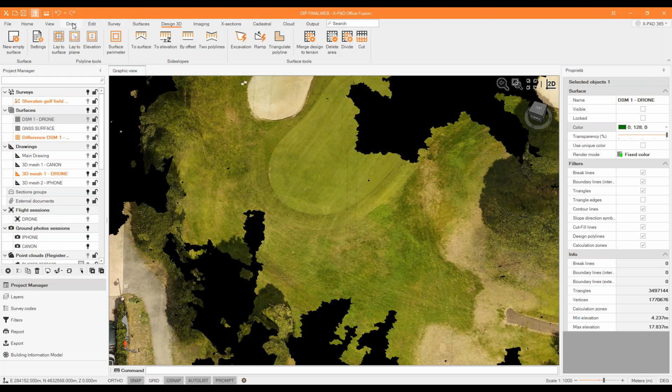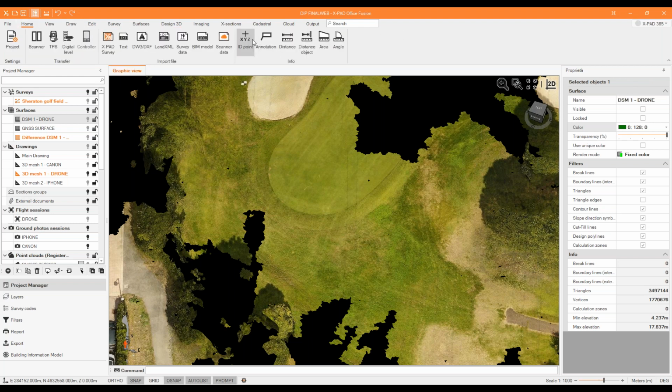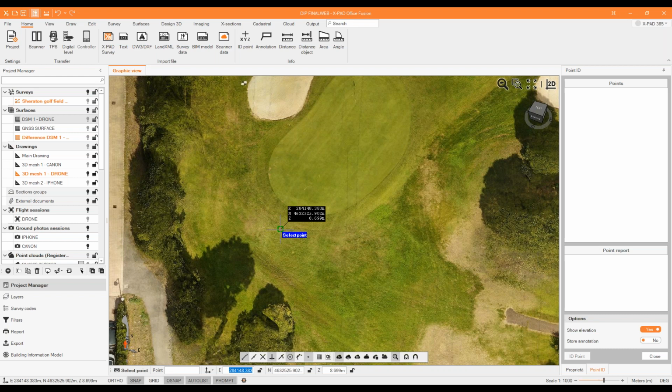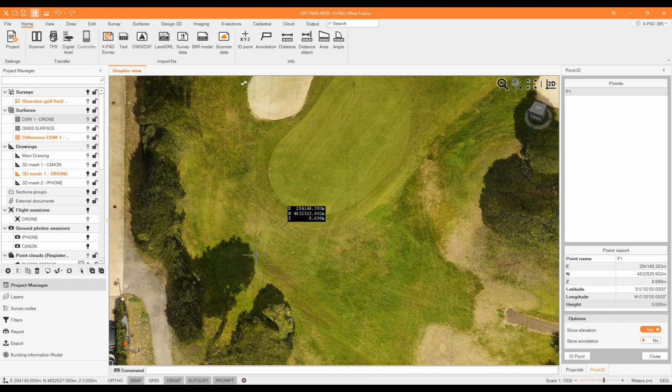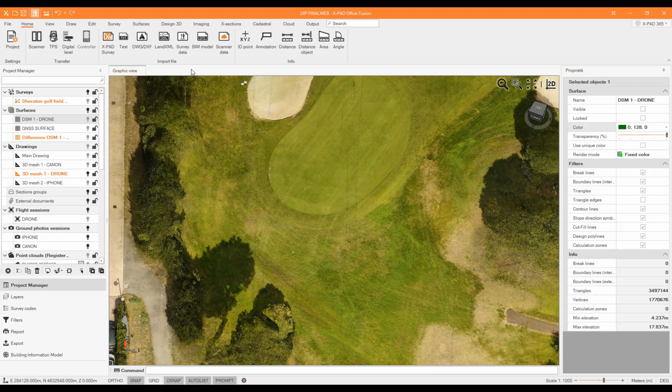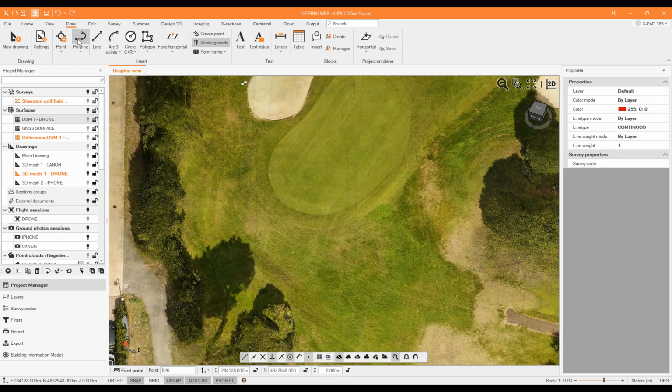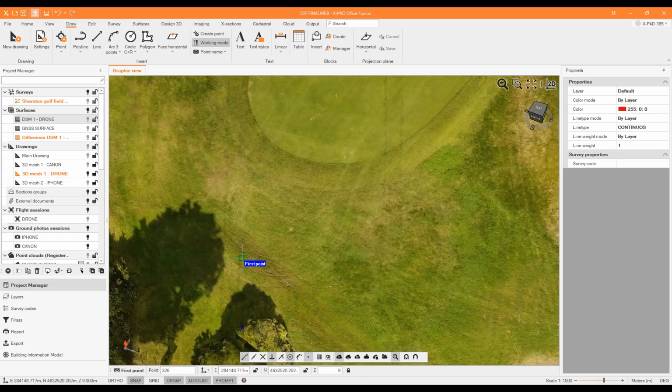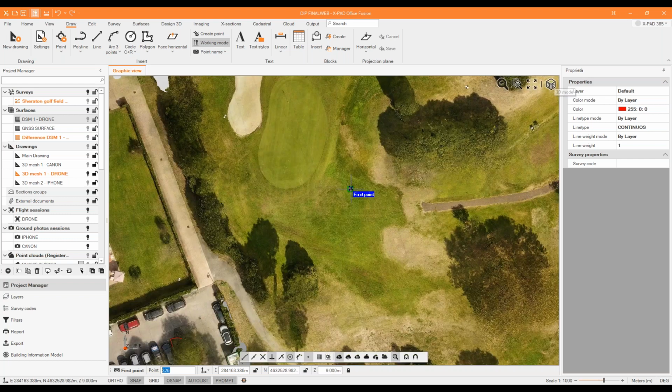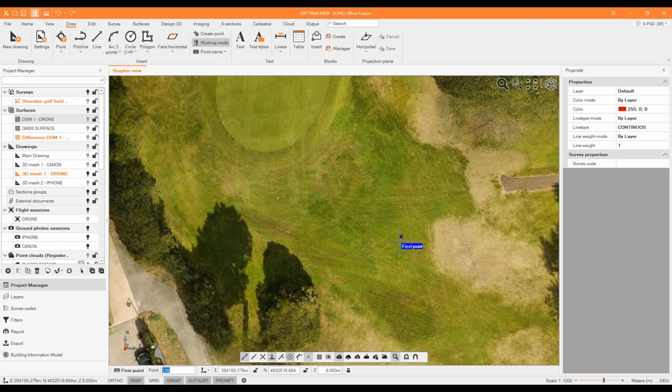So, drawing. First of all, I just want to check the elevation at this precise point, so it's 8 meters. So we can directly draw at a different elevation without using the snap on the drawing, and then use another tool from Design 3D in order to overlap the polyline on the surface. Okay, polyline. For example, since it was 8 meters, I can select 9, and now I can create the bunker here. 2D in order to be exactly orthogonal to this part.